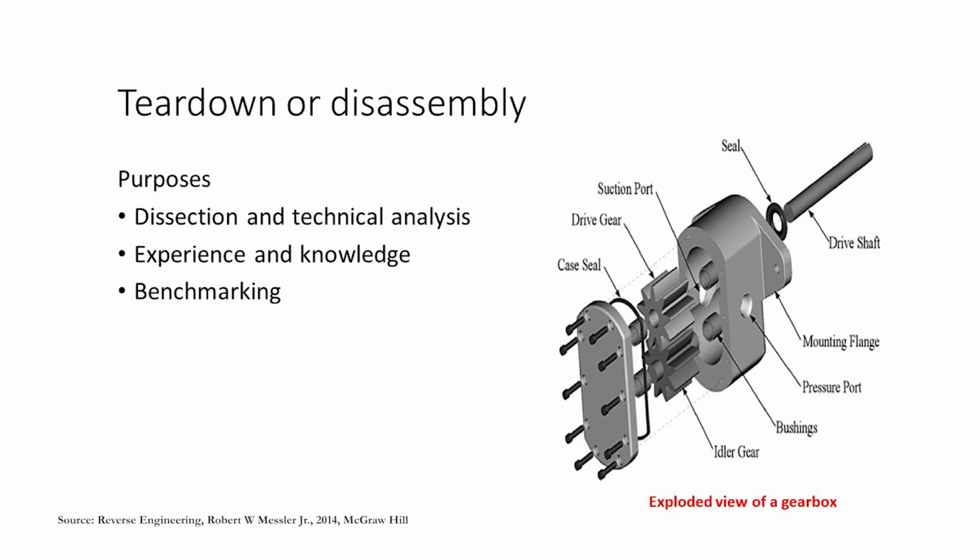This is a gearbox which essentially houses this gear, but it has to be housed in this box which requires all of these other components. This outer frame goes in together with the seal and pushes this gear into this chamber, and this chamber and this frame are locked together with the seal and these fasteners. Using these fasteners, this is kept in place inside this housing, and that is how you create your gearbox.